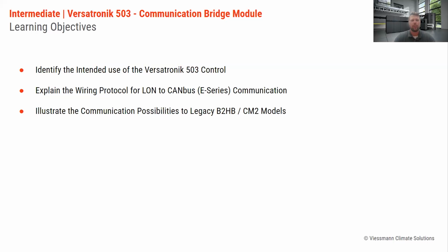And again, those communication possibilities are quite endless with all of our old legacy models. Again, even looking at that last slide with a Vitodens 100 or that electric VLN2 boiler that don't accept a 0 to 10 volt signal, we are able to do an outdoor sensor simulation. So we're able to adjust that temperature and output to the boiler as necessary.